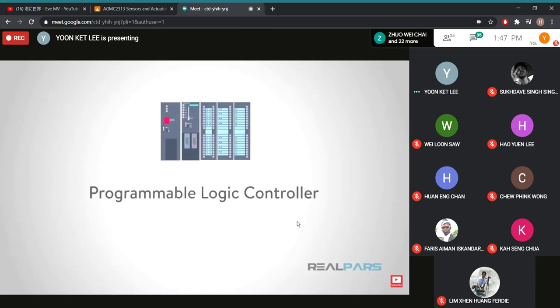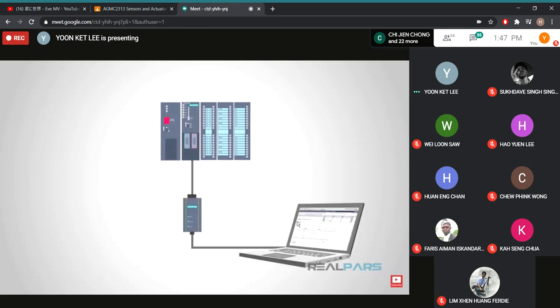Since this is called a programmable logic controller, we need to program it. Most PLCs are programmed using an application running on a standard desktop or laptop PC. They communicate with the PLC using Ethernet or a proprietary communication bus, depending on the manufacturer. Most manufacturers seem to have settled on Ethernet and/or USB in recent years.